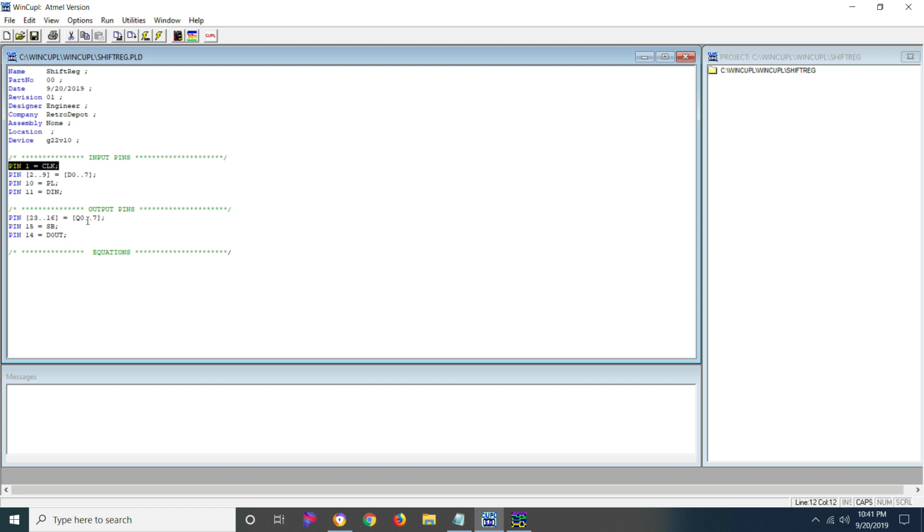You are going to have a period where the clock may be high if it's running as an oscillator, and your chip select signal may be low and it may go high again before the clock actually cycles low and high, just simply because of the timing difference. So you need to keep that in mind. It's kind of hard to explain, but you're going to have to do some finagling with this.